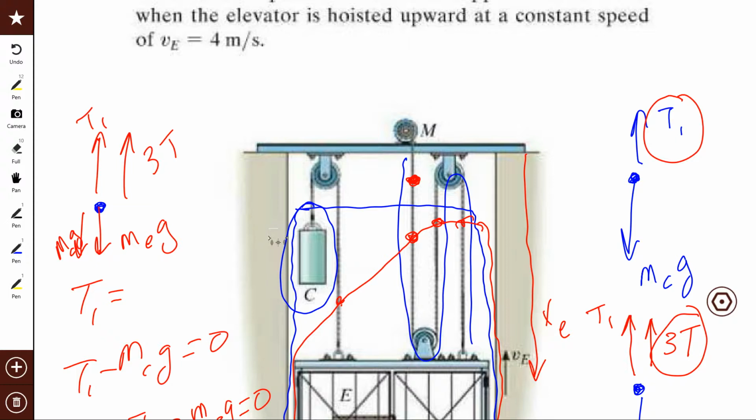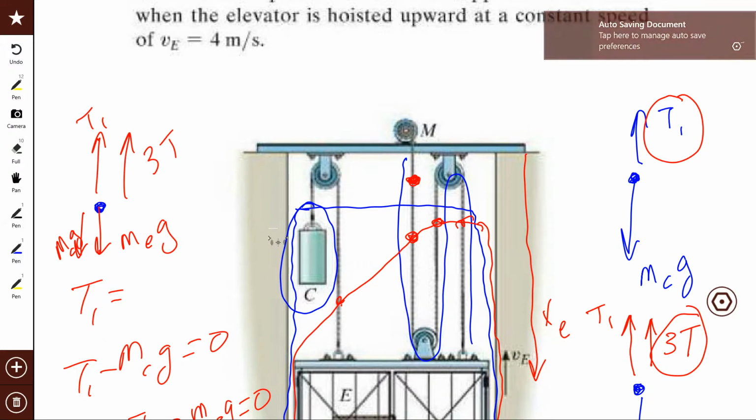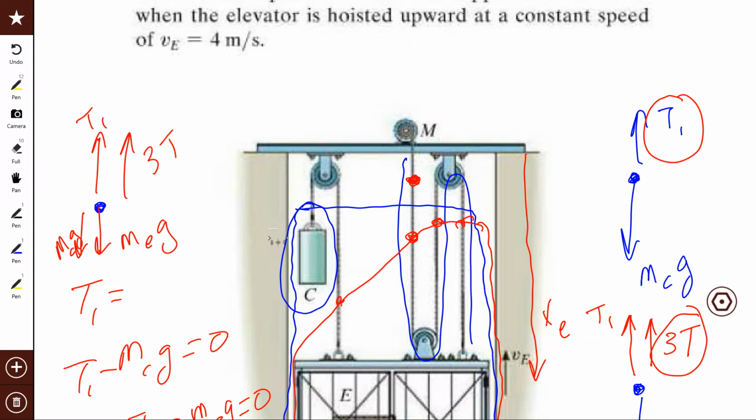Okay, yeah. Were we finding the velocity of the elevator? No, we're finding the velocity of what? The rope. So that's where the tension force is. Yeah, because if I'm looking for the power of the motor, I say, well, what's the motor doing? He's pulling on the rope. And how fast is he pulling the rope? I don't care about the elevator.